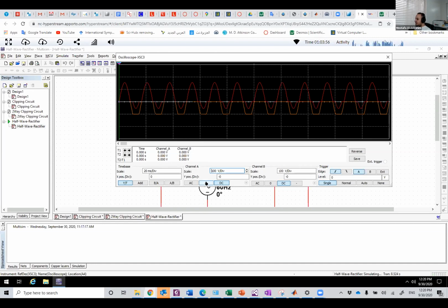This is basically the half-wave rectification, but there is no rectification anymore, because the diode becomes on in the reverse bias. Remember, the maximum voltage in reverse is minus 155, which is larger than minus 100. So the diode has made a clipping at minus 100 in the reverse bias.